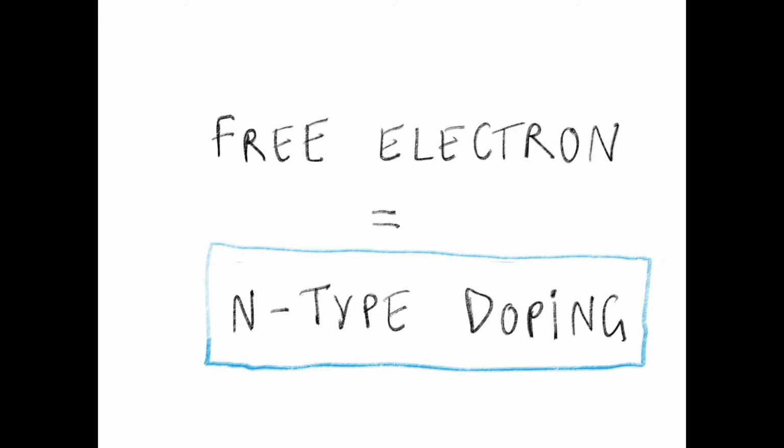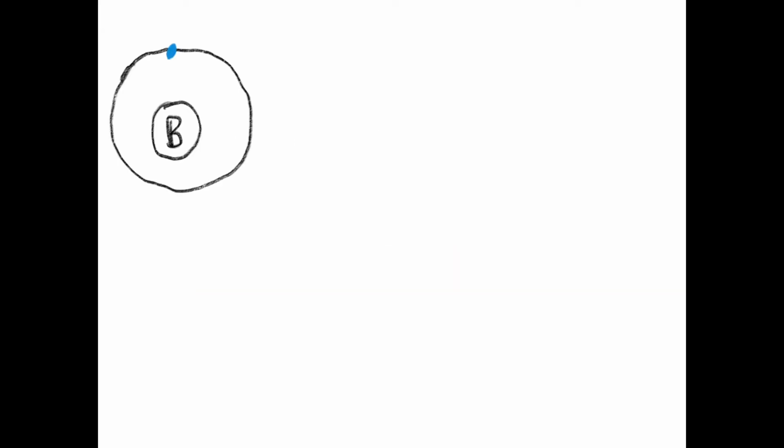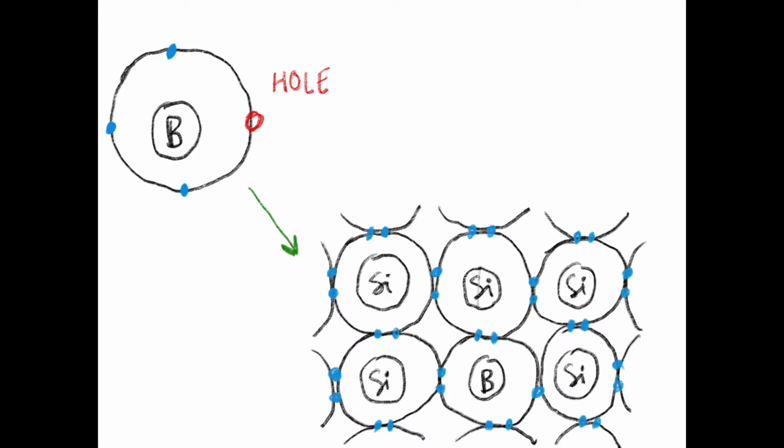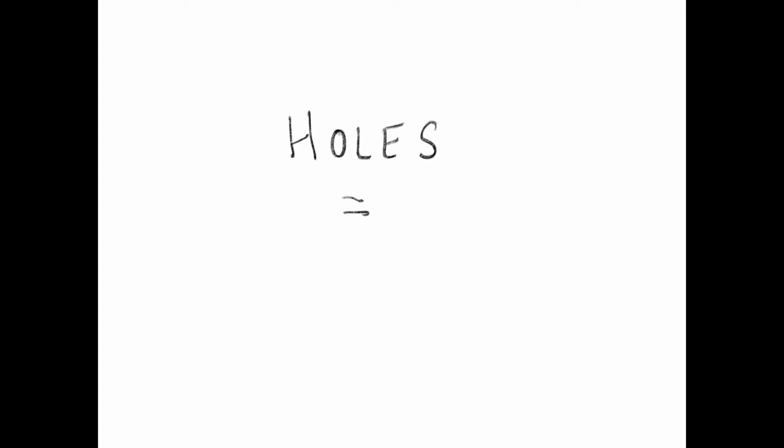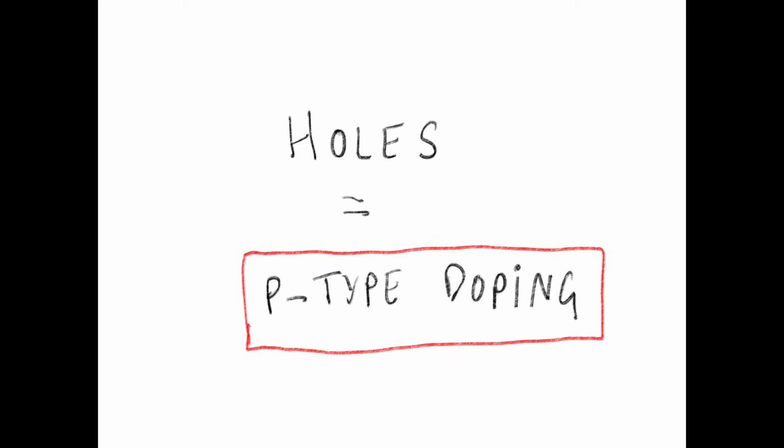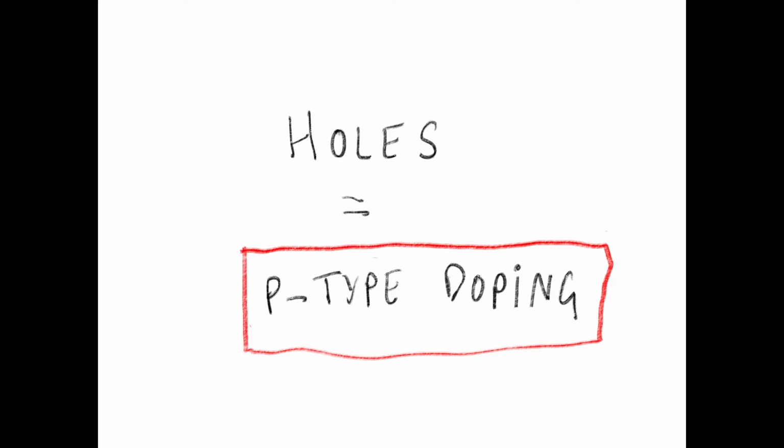Silicon can also be doped with elements like boron, which have 3 outer electrons, or 1 less than silicon. The gap due to the missing electron is called a hole, which has a slight positive charge. In a lattice, this hole means that there is space for electrons to move. This means that it is possible for current to flow. When a hole is introduced in a lattice, this is known as a p-type semiconductor, due to the slight positive charge of the hole. So what happens next?